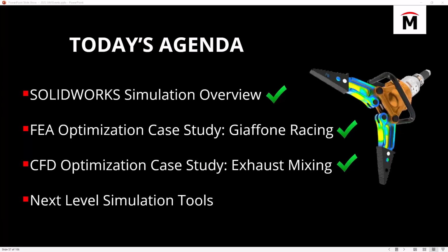Firearms for sure, suppressors, you know, as a bullet goes off and gas expands. What I would think about there is in flow simulation, our models themselves don't deform. So you can set up an explosion, basically a very high pressure event happening in a very short time span. And that's going to map to things like the pressure distribution on things. But those solid bodies themselves won't tear apart and explode. But you'll see all the explosive gases, and you'll see what the pressures and forces on those bodies were. Does that make sense?